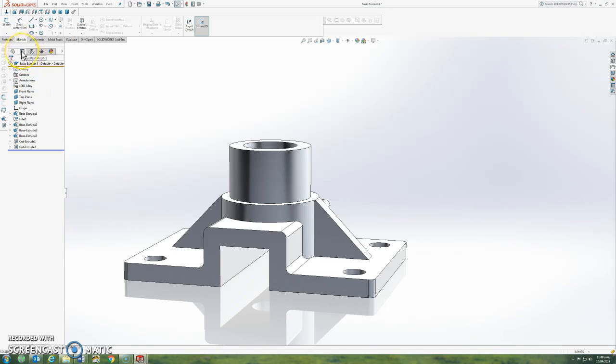Okay, Property Manager's here. Again, I haven't really used it. Configuration Manager is good if you want 2 versions of the same document. So say one would have 4 holes and one might have 8 holes or something like that. You can just choose between the 2 versions of the bracket and those holes instantly appear or don't, depending on what you need.